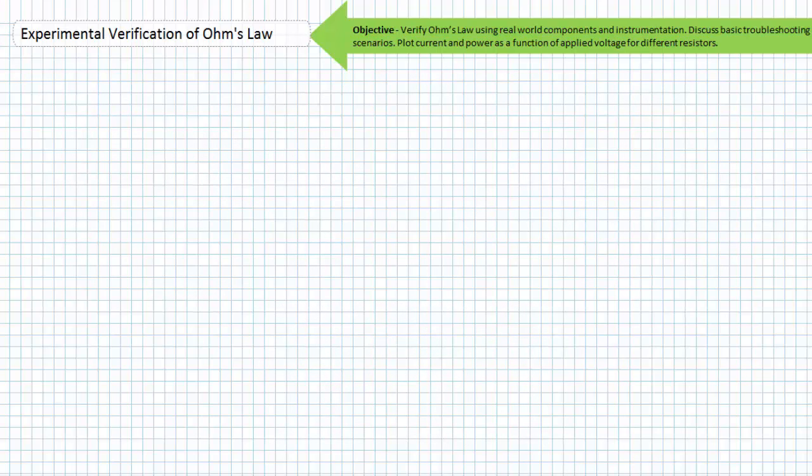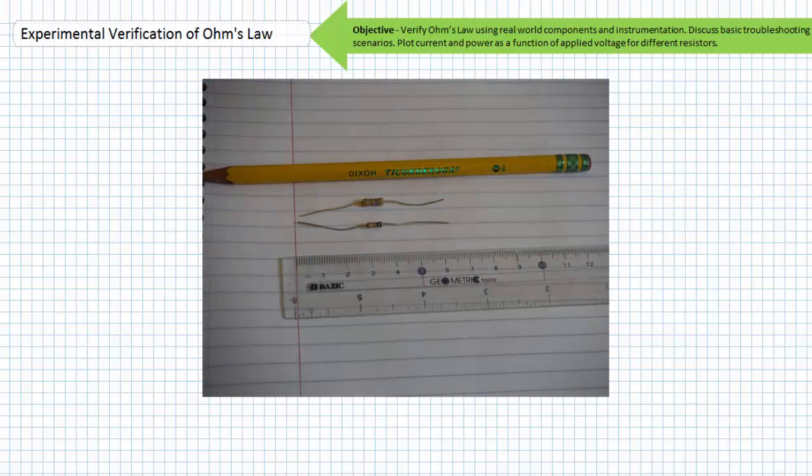But quick show of hands, who wants to see me set something on fire again? Okay, everybody's in agreement. Here we go. Here's two resistors with the following 4-band color codes: yellow, purple, gold, gold, and green, brown, gold, gold. The first one is a 4, followed by a 7, and multiplied by a 0.1, or 4.7 ohms. The second one is a 5, followed by a 1, and multiplied by a 0.1, or 5.1.